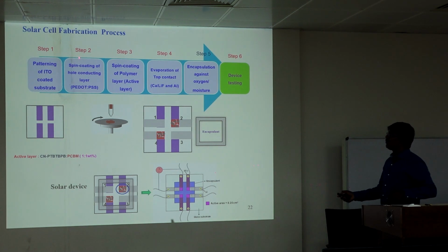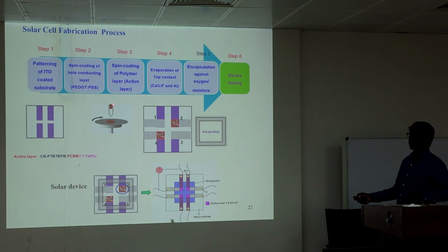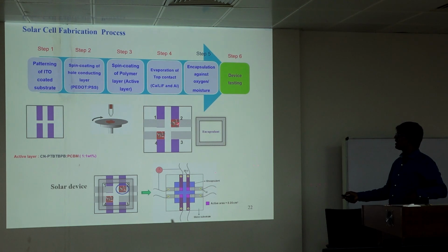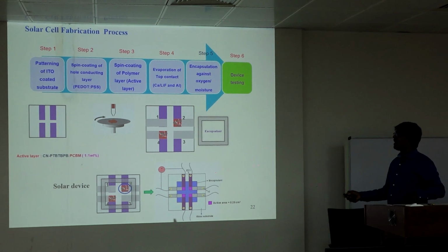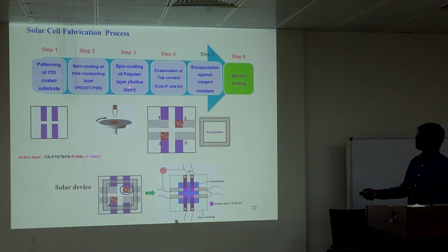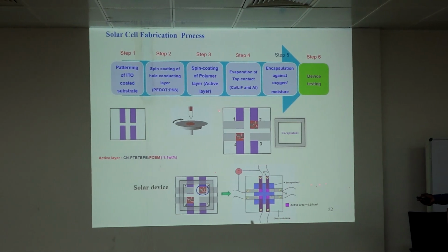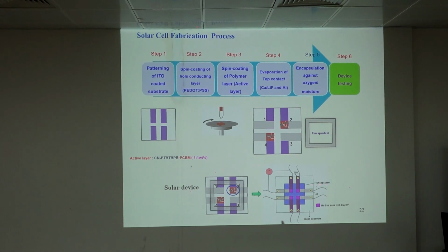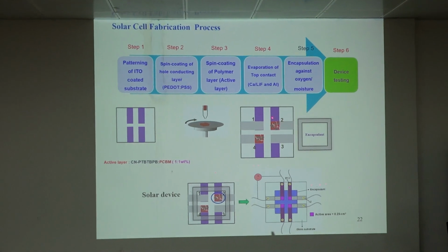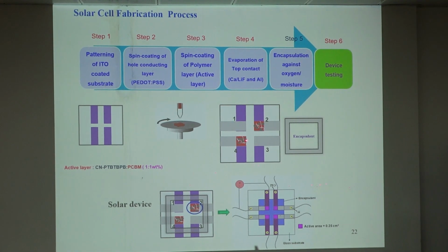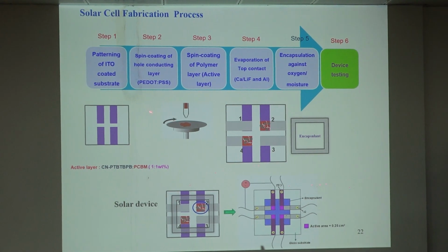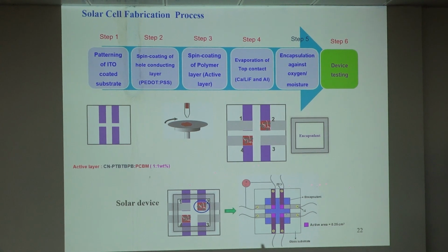Then we put your compound, spin coating of PEDOT:PSS. We drop PEDOT:PSS on the plate and then spin coat. So this may be like a red one, we get your PEDOT:PSS. After which we coat your polymer, that is your oligothiophene based polymer, the active layer plus PCBM, both combined, and then spin coating once again and it forms a surface. So 1, 2, 3, 4, 4 places we have to coat. We are coating on 4 places actually.